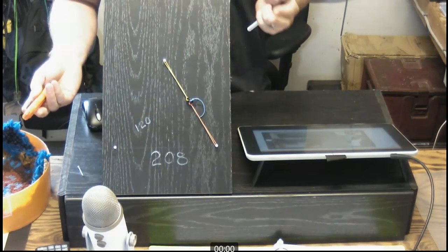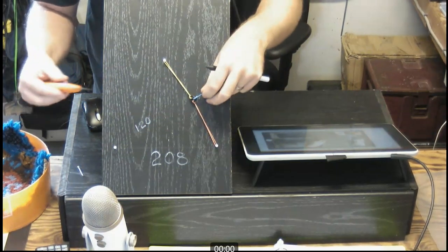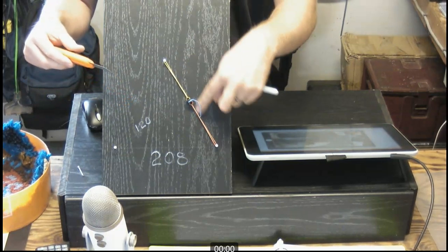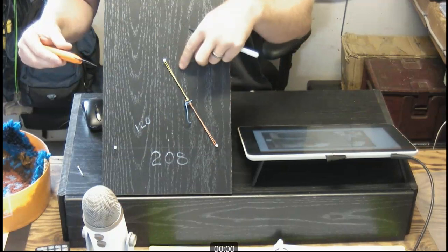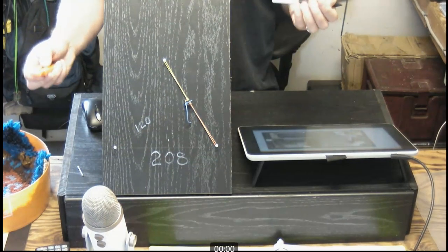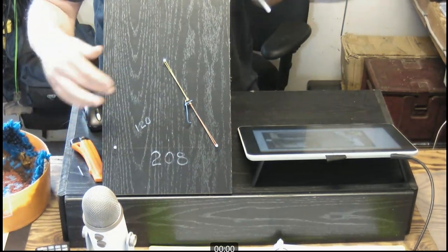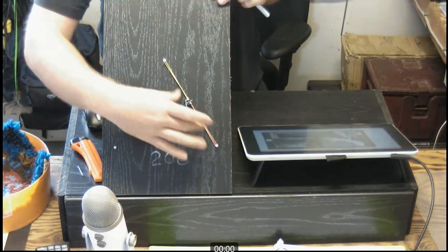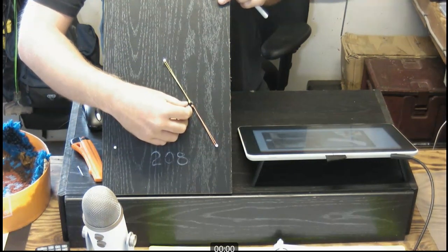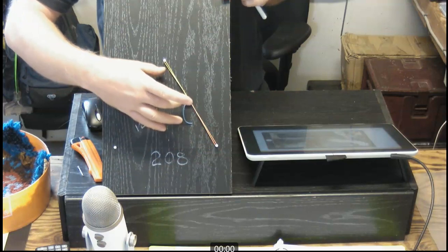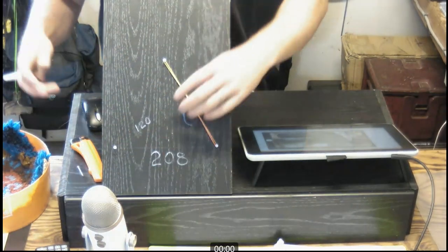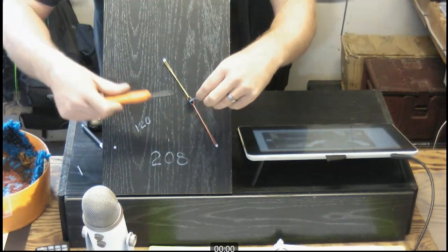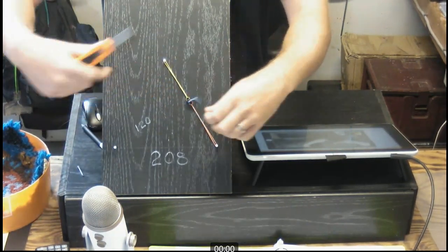As soon as we open that, we see that these two snap back across here. Once again, we said this was 208 volts from line to line over here. Because we have now opened that up at the 208 volts across there, these are now going to be centered across the middle, which is going to be 104 that we are going to see across either one of these. Just give me a second, we just need one more piece.